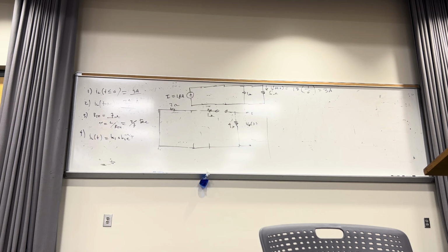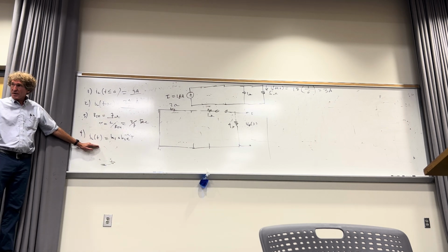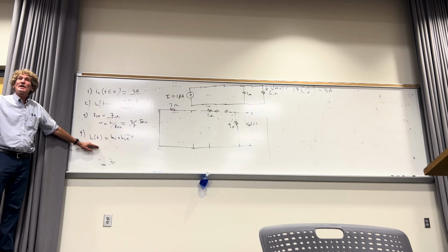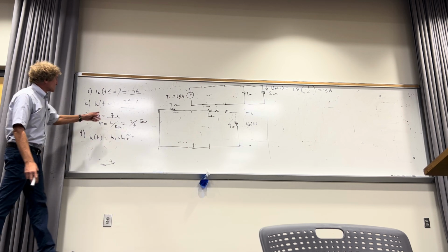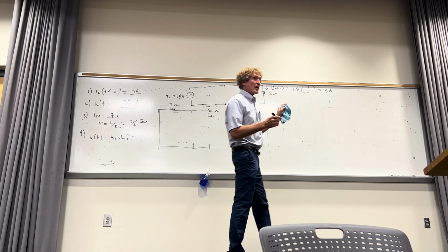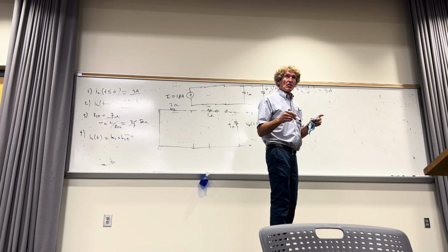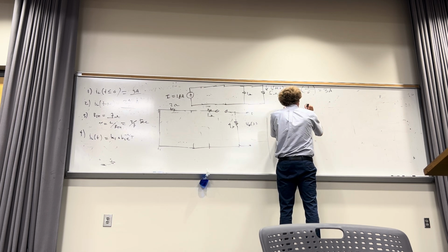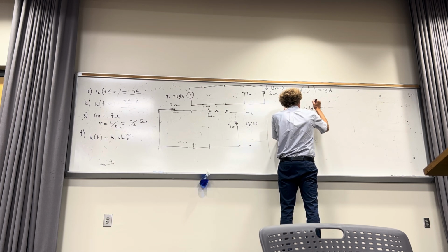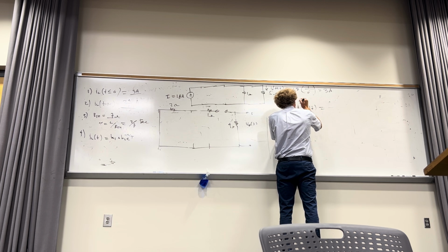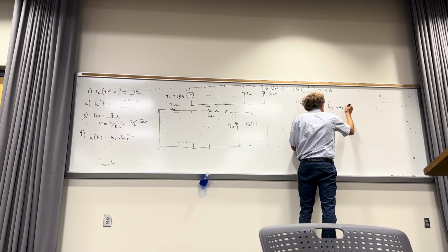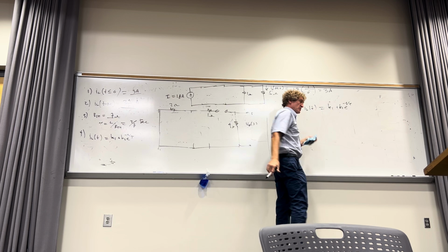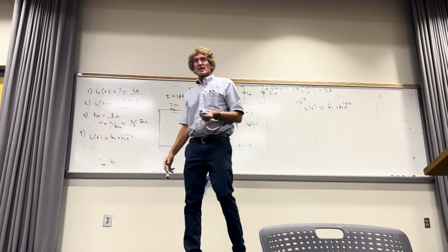Now this is important. Now I go to this thing, right? Now you're right about that, whoever said that. We know what K1 is, which is the current as t goes to infinity, which is this one. So now I come over here, I'm going to write the equation. I know that IL is a function of t, and this would be for t greater than or equal to 0, is equal to some K1 plus, I call it K2, e to the minus t over tau. We have tau. Do you agree with that? Make sure you see it.